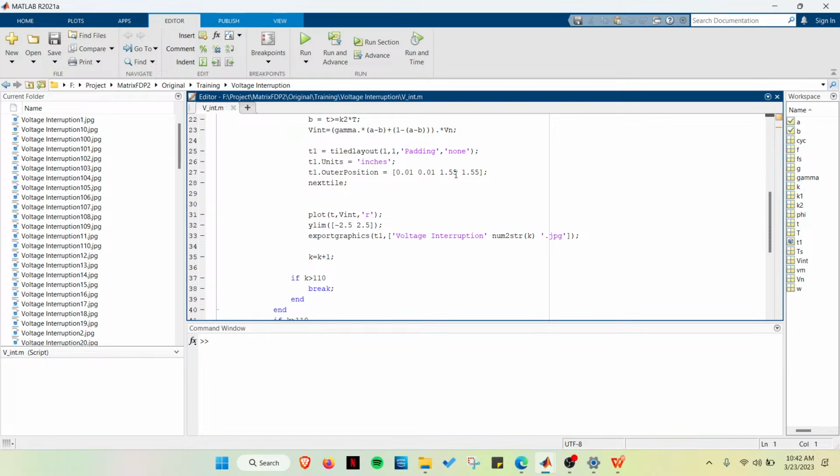Or else, when you are rescaling directly in MATLAB, and I am not sure about other software, most of the data is lost, because MATLAB is matrix laboratory. It will always use everything in the form of matrices. A large matrix can't be converted to a small matrix directly. It will leave some data so that it can convert the large size to the smaller size. So I'm using this smaller size so that I can easily get my required output.